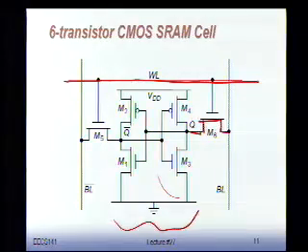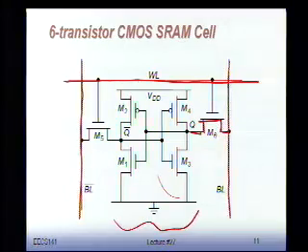Okay? So now, the bit lines, this is a symmetrical structure. So we see that for every cell, we're not going to provide 1 bit line, we'll provide 2 bit lines. We actually make it differential, in the sense that every time you're going to have bit line and bit line invert. Because as you know, a flip-flop always has Q and Q bar. So you're going to use that to actually save power and make the cell smaller.